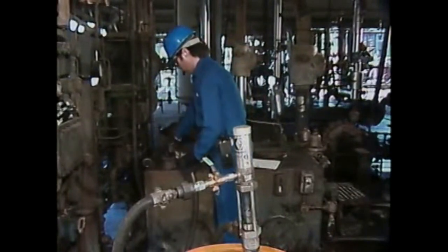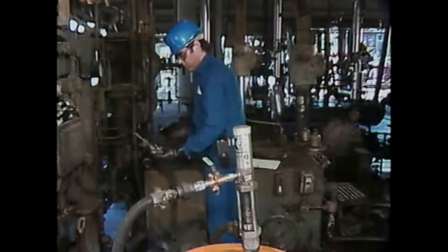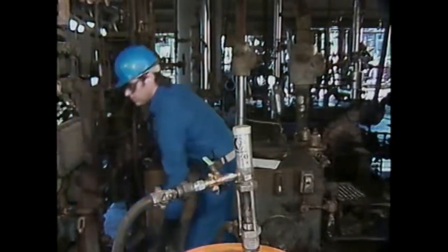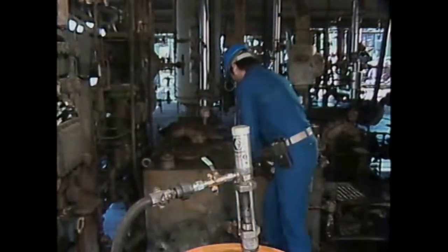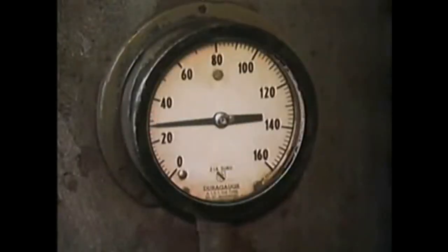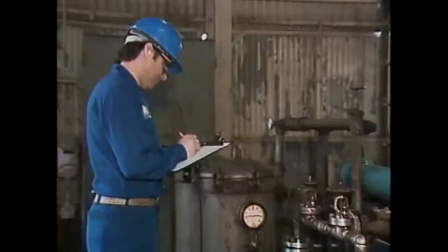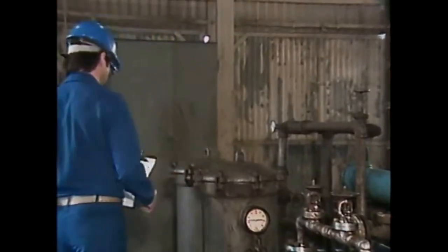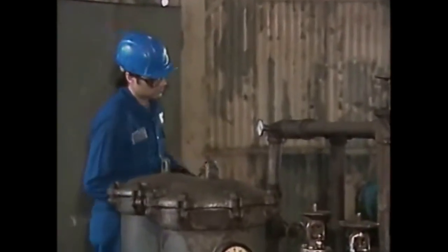It's a good practice to note when oil is added and how much. If oil has to be added frequently, it probably means that an oil leak has developed somewhere in the compressor system. The oil pressure should also be checked. Low oil pressure can be an indication of several possible problems. Low oil pressure may indicate an oil pump malfunction or an oil leak. Higher than normal oil pressure can indicate a clogged filter or blocked oil lines downstream of the gauge. Check the oil temperature too. If it's too high, there may be problems with the lube oil cooler.